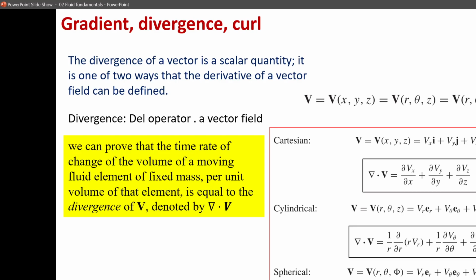So let's think about it this way. Let's use a combustion example. Let's say you have a fuel droplet, and you combust it, right? What is going to happen to that droplet? A big fuel droplet, right? It is going to shrink, right? Its volume is changing, right? Taking the divergence of velocity specifically is going to tell you the rate of change of volume of that liquid droplet, of that fuel droplet, while it's shrinking. Does it make sense?